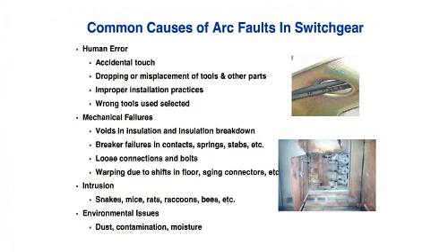All right, the causes, and I touched on some of them already, but human error, I think, is one of the biggest issues. Why? Because as some maintenance people are racking in breakers, for instance, they will try to what we call over torque the racking screw. When that occurs, the breaker has a tendency to jump, or it has a tendency to compress and crush.